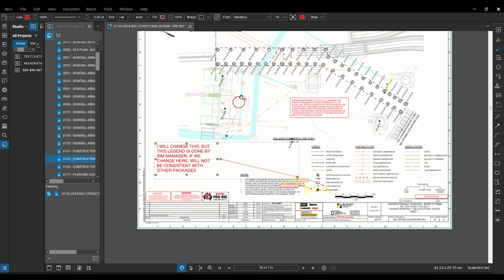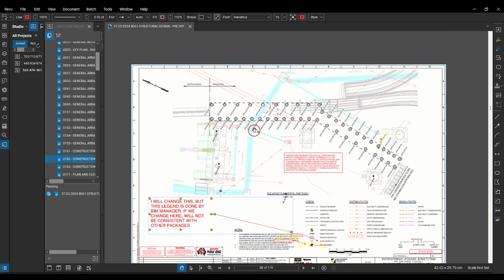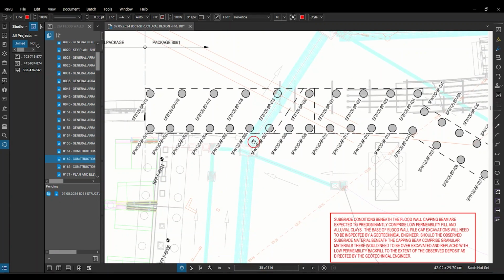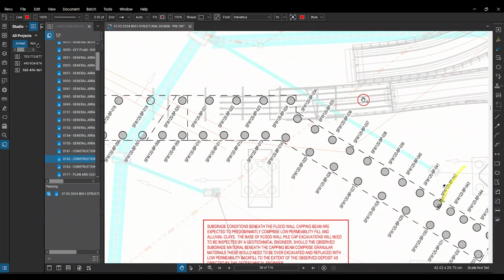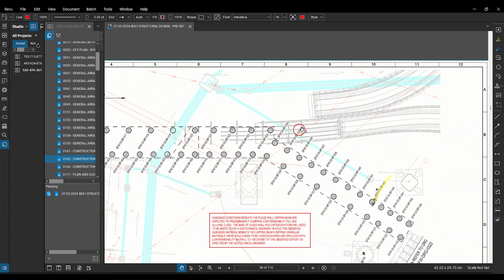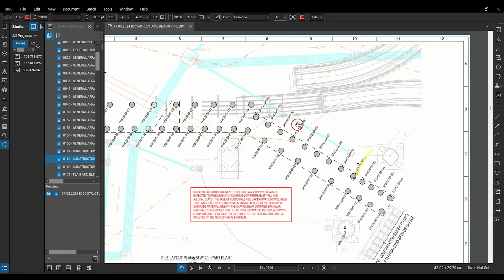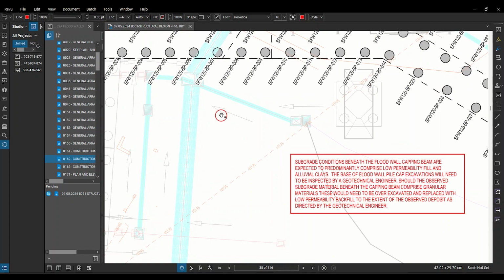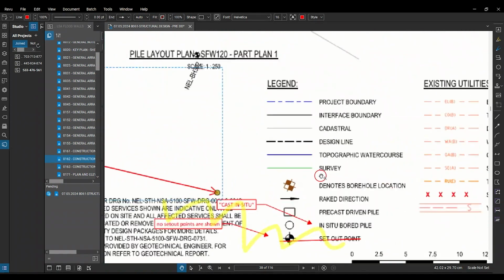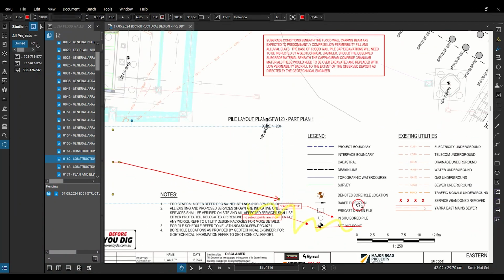So we just fixed the penetration for this blue pipe, which is a drainage. We just picked it completely random. Maybe this one also is a problem. So this one is actually going top of the wall, so there is no clash here. But it's always good to check. I'm sorry, I'm really not sure what the meaning of these arrows is. Is it a rack direction? But anyway, the engineer asked me to delete it.